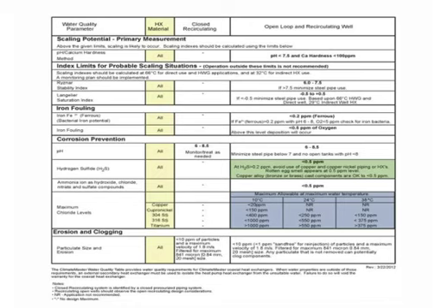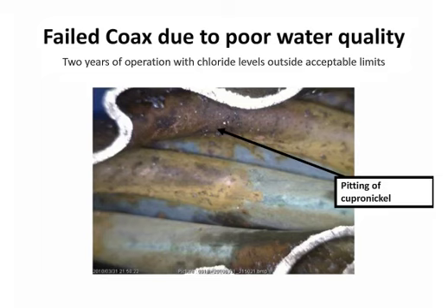And again, depending upon the amount of chloride, if I was going to proceed with the project, it might even be a titanium, because this is still less than the cost of a ground loop system, so you still have a good candidate. So again, pay attention to the independent testing lab results of the water you're dealing with, and make sure you're applying the correct kind of heat exchanger so that you don't install a problem down the road.